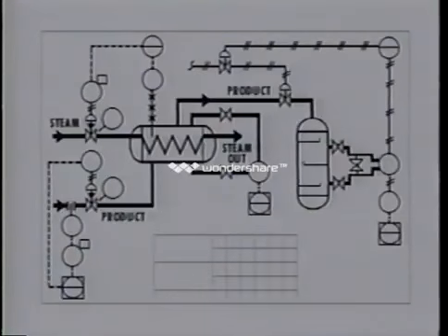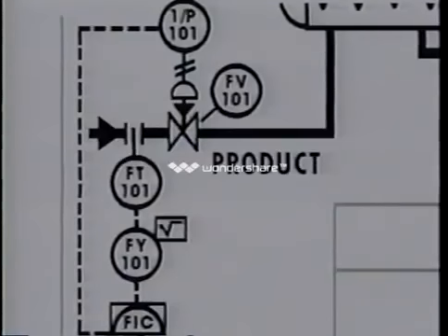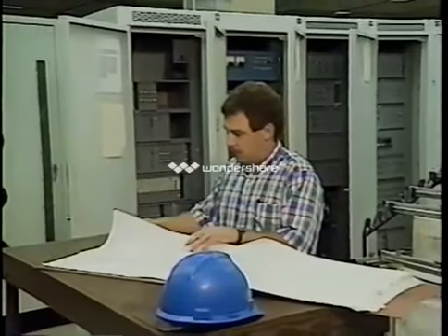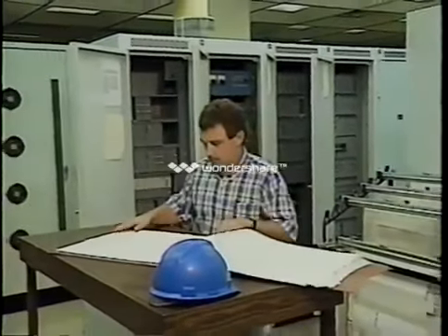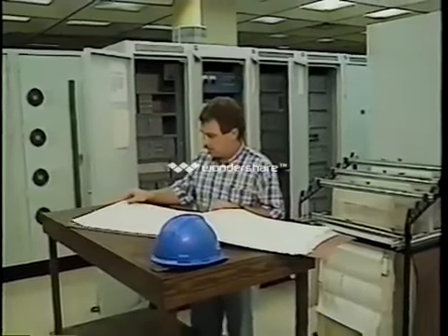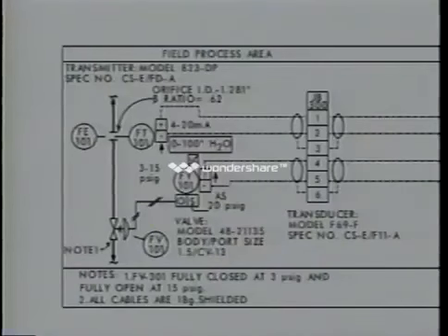First, look at a P&ID to identify the loop. Here we see loop 101. From the symbols, you can see this is an electronic loop that controls flow. Check the title block on both the P&ID and your loop diagram to be sure they match. When you first look at the loop diagram, it may appear complicated. Let's look at each section to see what information is available and how to use and interpret what you see.